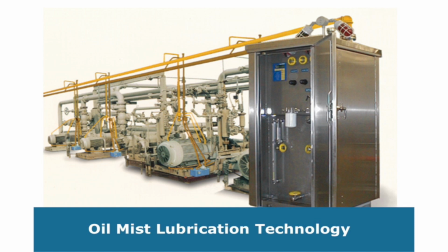You can see electric motors in the foreground. And usually these electric motors, of course, are driving pumps. But as you will see later on, other machines are connected to the oil mist system as well. But the second header is the return header. In other words, any oil mist that has gone through a particular bearing in a particular machine, after it has lubricated the machine, can be recollected. Instead of being sent off into the atmosphere, we can collect it. We can recondense it, and we can reuse it in many cases.